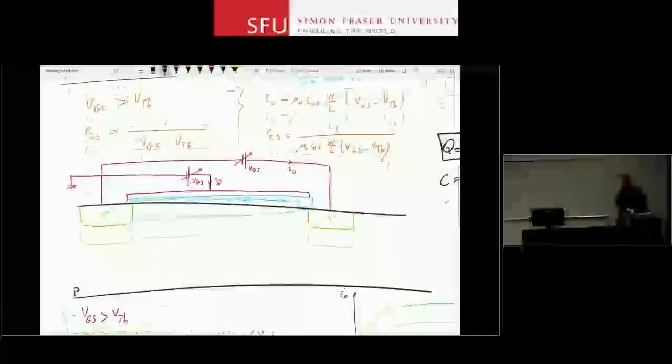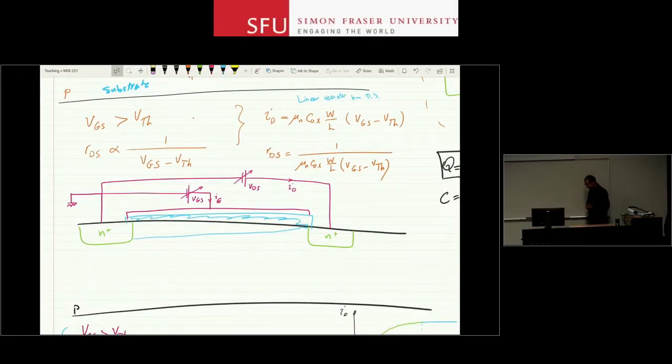Now, if you go back and look at the structure of a MOSFET for a second or two, you realize that we actually have another terminal. So let me maybe mark it with red here. This is one terminal, this is one terminal, this is one terminal. So that's the three terminals that I showed you on that symbol. But there is another terminal. There is another node here in this circuit that has to be connected to a voltage, and that's this substrate, right? You cannot have a floating substrate. So a MOSFET in reality is a 4-terminal device.